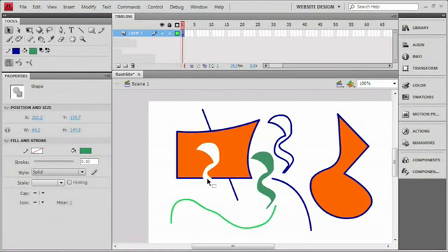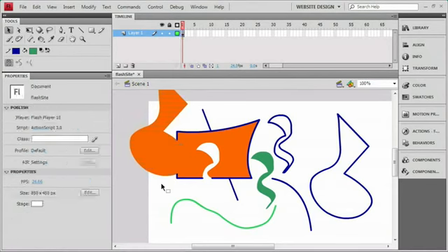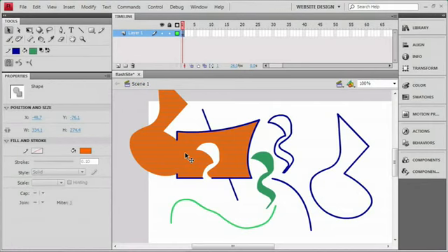We can see another kind of merging go on when we have two objects that are the same color. So let me grab this object over here. We've got that fill shape. Now I didn't double click, so I don't have these strokes here, and I'm just going to drag that over and drop it on top of our rectangle shape that we had from before. Once again, while it's selected, it's kind of floating, but as soon as I click away from it, it's going to delete anything it's on top of, which will be that blue stroke here. But since my two fills were the same color, instead of cutting them apart, it's actually joined the two together. So if I click on this, you can see that it's all one big fill.